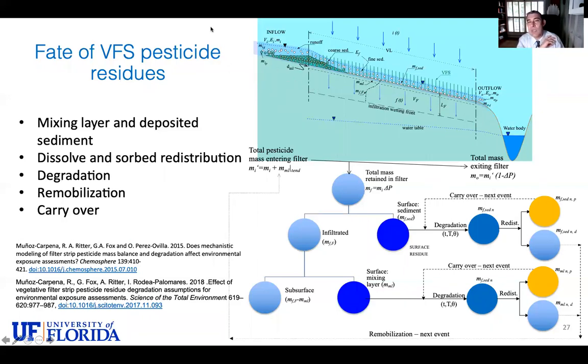There are models that do the transport and generation of sediment, water, and pesticides on the field. There is an Environmental Protection Agency model, PRZM, that does all this part in here. There are models that do the water body dynamics, settling, and degradation in the water column: EXAMS, VVWM, also EPA models. And now there is our model in between to do all these things, okay? So ultimately, the important outcome of this analysis is the concentration in water, because that's where the non-target organisms are, amphibians, larvae, things like that. So what they do in this model analysis is calculate numerically, daily, the concentration in water, and they look at whether it exceeds a threshold for different indicator organisms, okay? So the focus is in here.